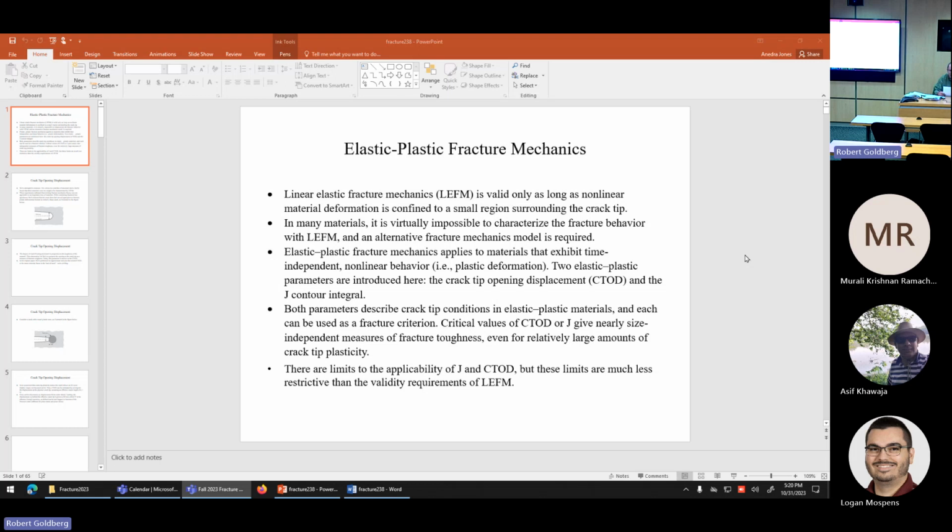The first one gives a little bit of information, and what I want you to do is compute the plastic zone corrected stress intensity factor using Irwin's correction and the strip yield model. We covered that right before the midterm, but it wasn't covered on the midterm. So I want to see the equations. I don't want to just see a table. I want to see the equations and a little bit of the work.